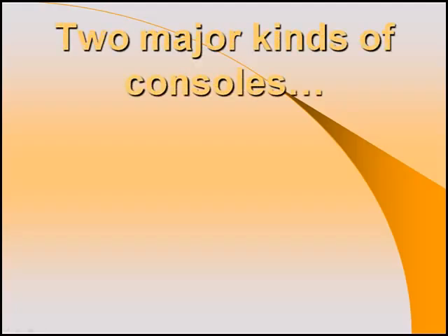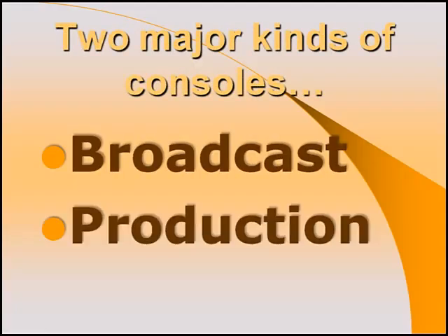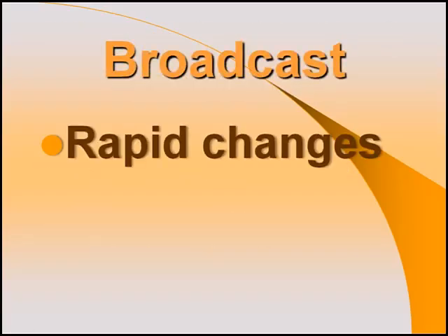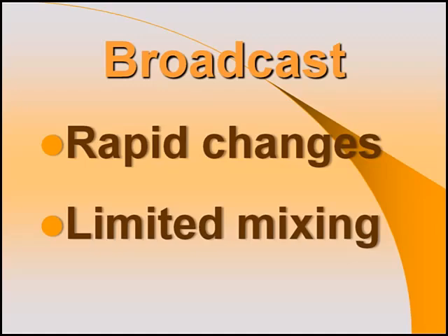Very broadly speaking, there are 2 major types of consoles: broadcast consoles and production consoles. Broadcast consoles are designed to allow rapid changes, and they have limited mixing capabilities. If you're on the air live, you want to be able to make those changes quickly, and generally you will probably have no more than 3 audio outputs at the same time.